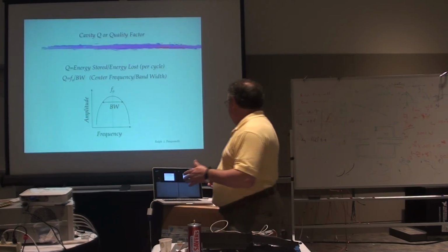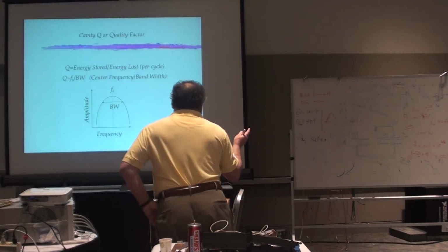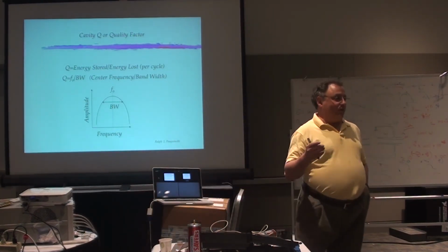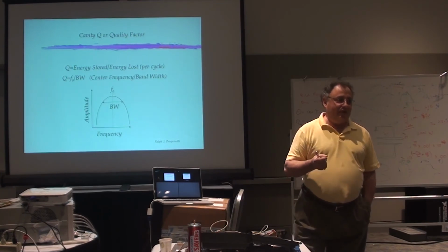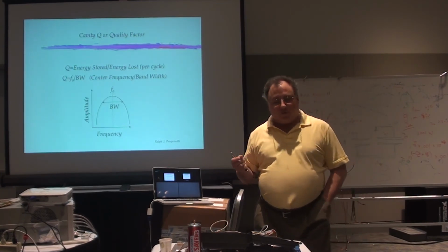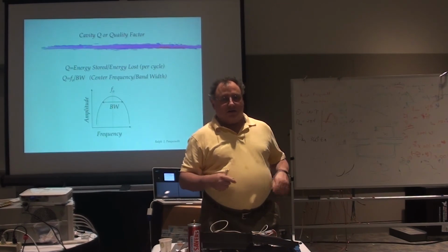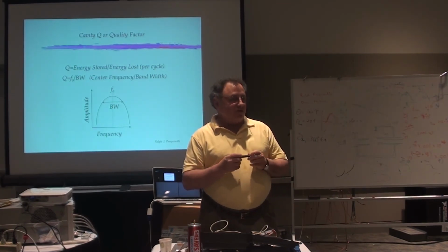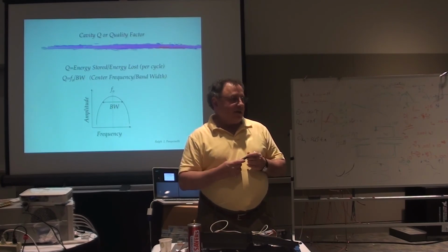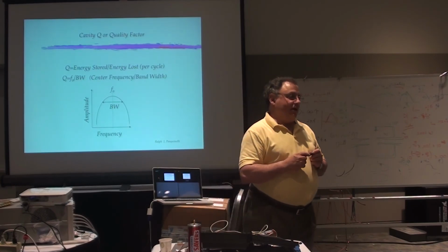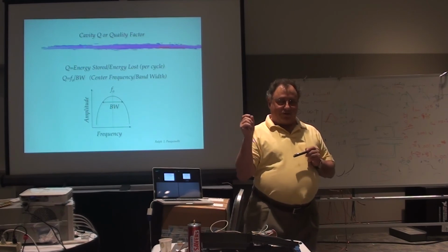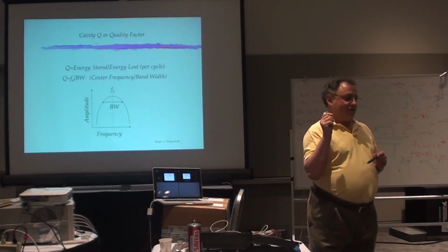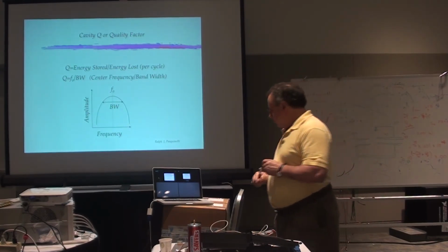There's more to go. And bandwidth. In the case of a cavity, you may not need that much bandwidth because you want high volts. So cavity systems are typically very narrow. In normal RF systems, as I said, cavity in copper, 20, 30,000 is possible. But when you start getting to superconducting, Qs can get into the million and 10 million. And now you can think the bandwidth, depending on what frequency you're operating at, is no longer kilohertzes or tens of kilohertzes, it's tens of hertzes. And that presents some real issues that we'll talk about.